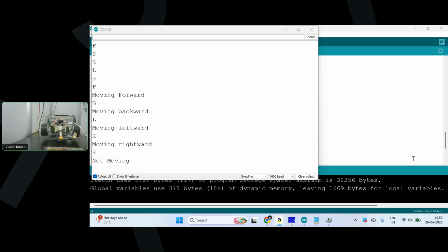Okay, James, a good question. See, when we talk about the IC, currently I have connected the USB cable to this board and it was the Uno board, right? When we program the IC individually, first of all, you need a programmer. You can't directly connect the IC with this USB. You have two options.